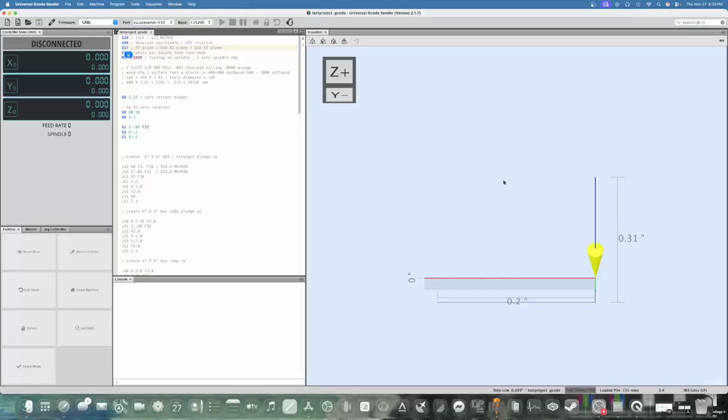And if it comes in a situation you need to change it to G18 or G19, once you're done with that specific arc move, put it back in G17, because if you come across another arc move you meant in X and Y and it's in 18 or 19, the machine will totally mess up trying to calculate that arc radius.